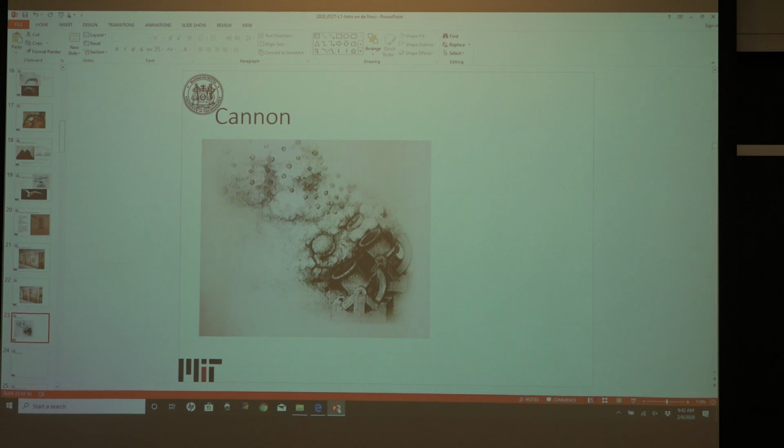On the engineering side, we went from directional alloys to single crystal alloys. As you increase this turbine inlet temperature, and I'll pass these around so you can look at them, with the technology today, the engine blades actually operate beyond their melting point.